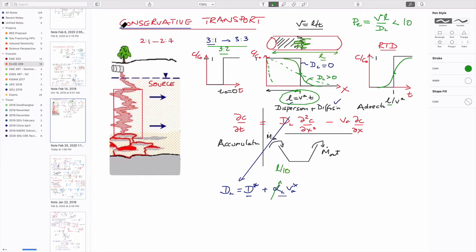And so now everything for those was what we refer to as conservative transport. Everything that gets dissolved from this upstream zone and gets put into the flow tube remains within the water all the time until it comes out at the other end. But for some of these components that get transferred downstream, there's an opportunity for them to sorb onto the grains.